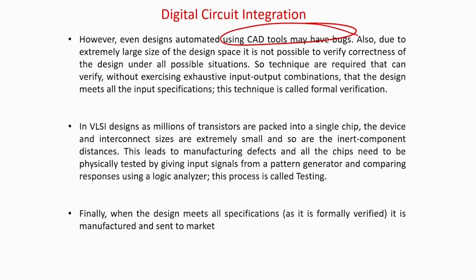So there is something called formal verification, because checking all possible input conditions is almost impossible. Think of a 128 bit adder: all possible input combinations will be 2 to the power 128 plus 128 plus 1 bit carry, an exponential problem. You can never solve that in a reasonable amount of time. So we have to check it formally. Formally means we have state based modeling, and mathematically you verify that whatever was given as specification has been implemented at the transistor level or gate level. At each intermediate translation stage, you have to verify it. That is called verification, and it is a very important part of VLSI design.